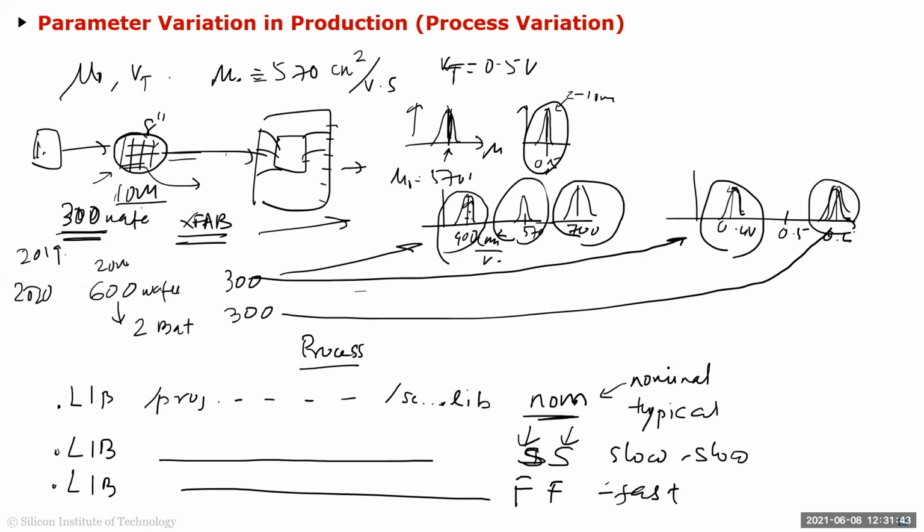Okay, so in our lab today, because we also get introduced to Python to automatically extract these parameters, so we can do it fast, today we are going to do this process and use a Python script to extract these parameters, and you can see how they're varying over process and temperature. So when you start going into the VLSI industry, you're going to hear this PVT term a lot. PVT. Have you done simulations over PVT?